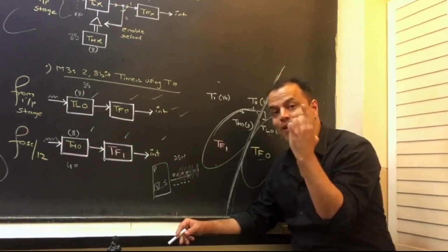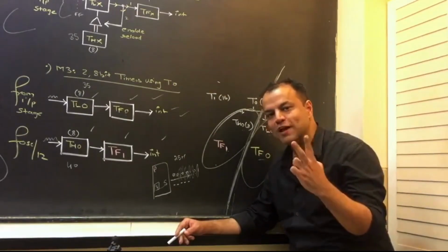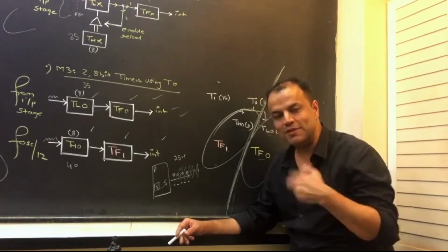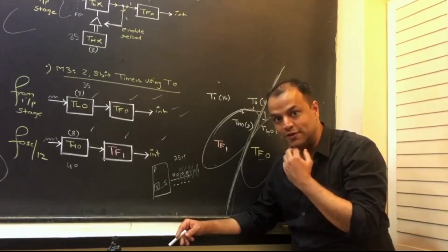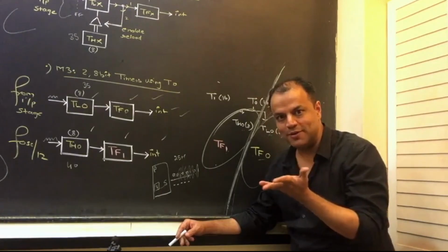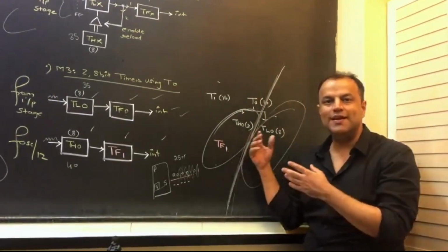That means you have only one timer now. Timer 0. All this while you were telling the whole world, I have 2 timers. Whoever wants 2 delays, come to me, I will produce it. Now suppose somebody comes and says, we've heard you can produce 2 delays together. You have only one timer, you don't want to be red-faced. What do you do? You split your timer 0 into 2 independent 8-bit timers.